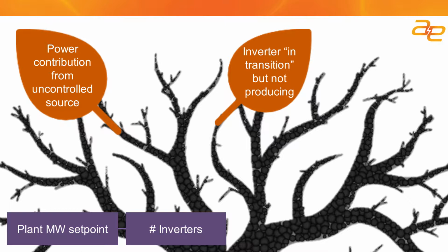I've got to keep track of that, because even though it's waiting, warming up, in grid sync mode, not delivering power, when that 5-minute timer expires, that inverter is going to jump to the command that it's being given. Where I see trouble with this most frequently is if somebody's doing maintenance at a big solar site, and maybe a feeder breaker is open. Now there's 20 megawatts of inverters that aren't running.